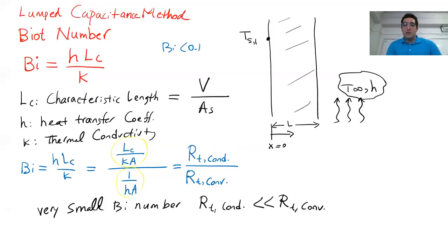Correct? For example, if you have a spherical copper object, because the thermal conductivity k inside the copper is so high, the resistance by conduction is really low compared to a wooden or plastic object where k is low. And on the other side, the resistance by convection is high when I have a stagnant fluid, when there's no movement inside the fluid, h is low.